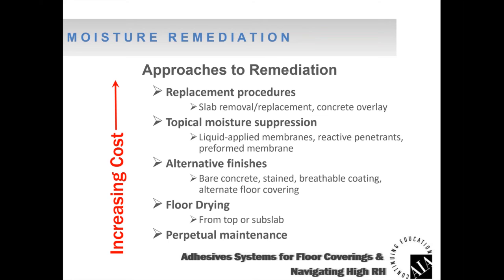You could look at alternative finishes, just leaving the concrete bare, letting the moisture evaporate out into the air. Some people think that we'd want to do stained concrete or a breathable coating, but sometimes there can be aesthetic issues because that excessive moisture drives the salts to the surface, and if you have a decorative floor, you get whitening or milking out or cloudiness of the sealer because of the salts coming up. The most common thing to do is a topical moisture suppression membrane, an applied membrane, a two-component epoxy material, very common.